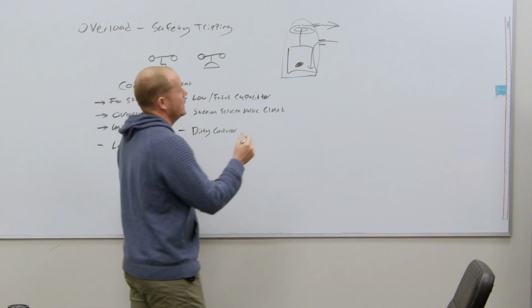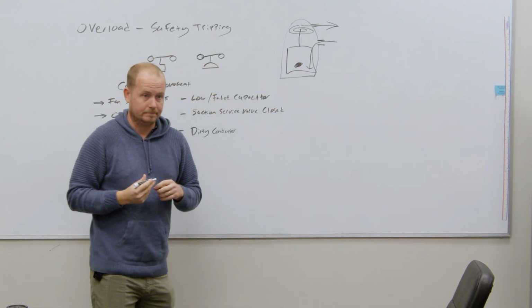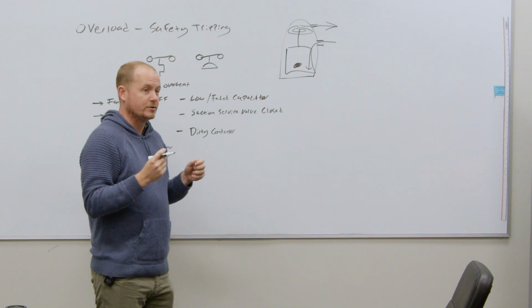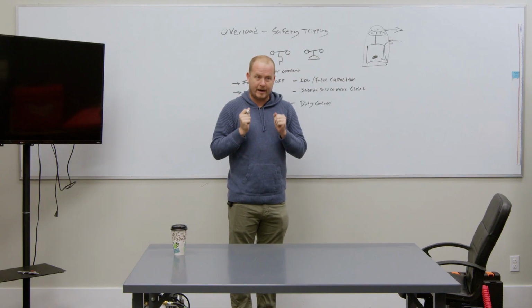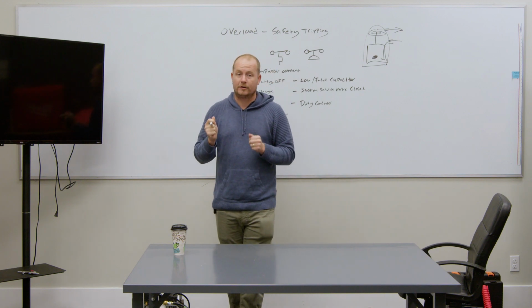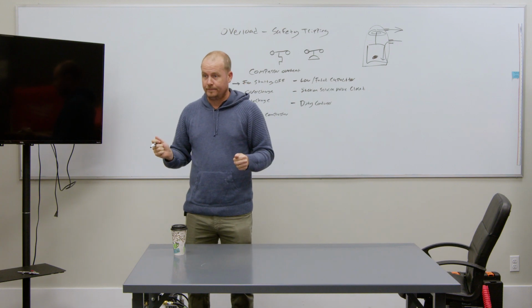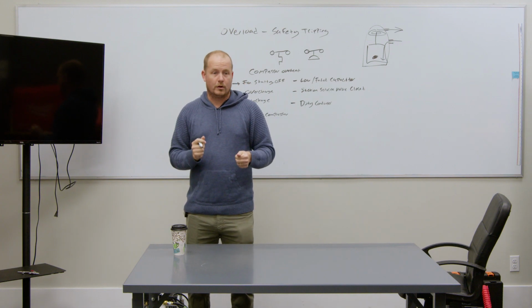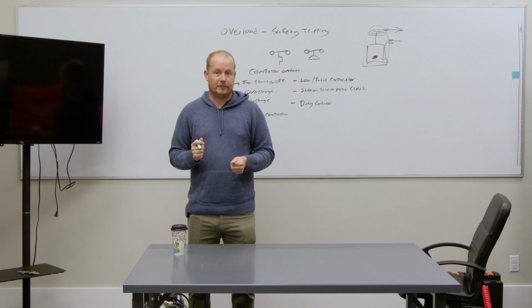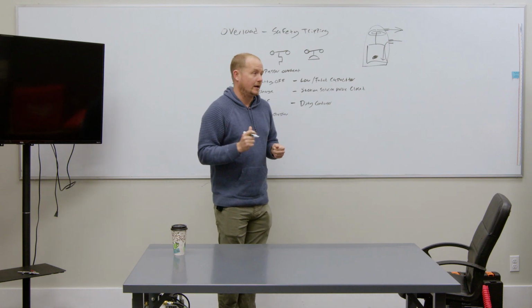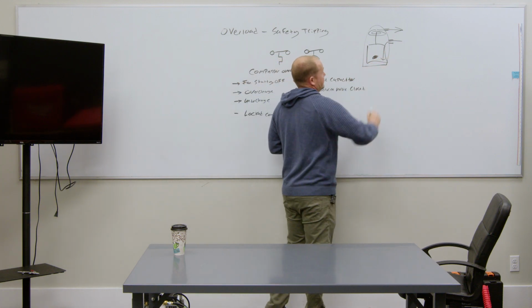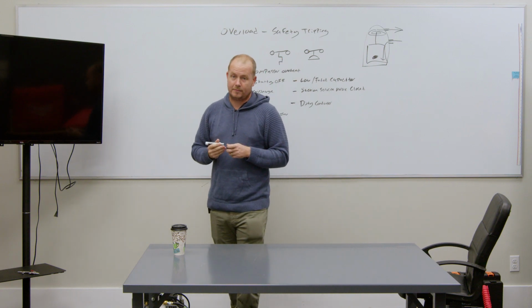But the point being that when you have a wiring problem or a locked compressor or any of those sorts of things where the compressor isn't running and overheating, it's just the windings heating up, it resets pretty quick. That's why when you have a failed capacitor, which we have all the time, have you ever wondered why you don't have to run water on a compressor in order to get it running again after a failed capacitor? Or generally you don't? Even though that compressor was sitting there going out on thermal limit. It's because that heat was isolated to the motor windings down at the bottom of the compressor.